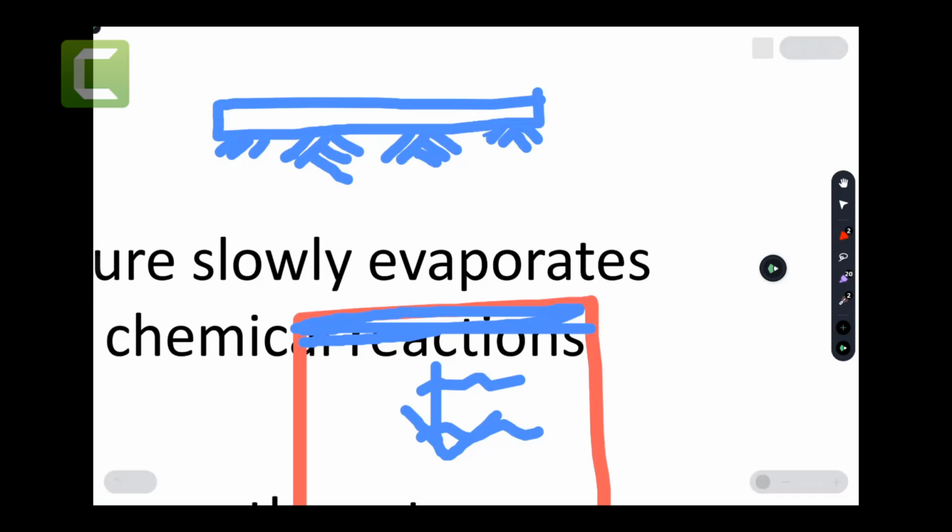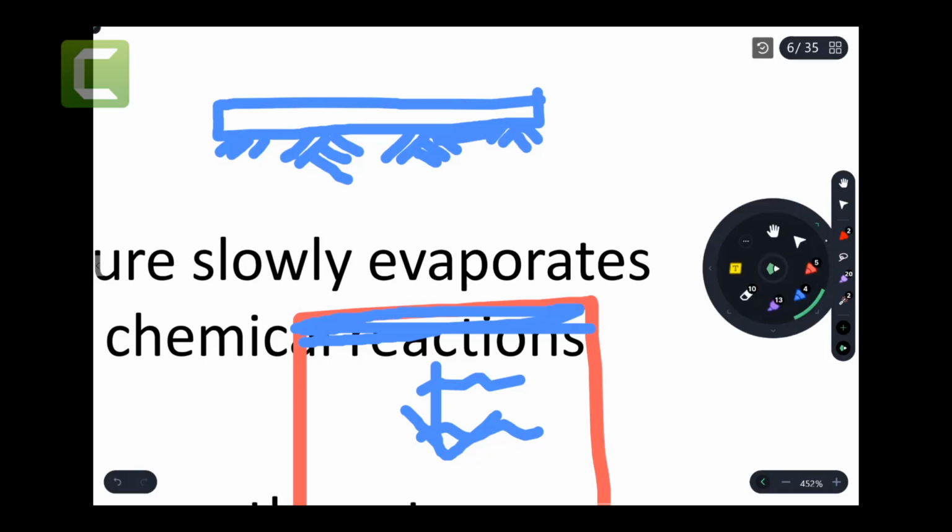However, there is actually friction. There is friction between the gray concrete and the soil, the dirt. And that friction is causing, as you know from physics, a resisting force. That resisting force can still be considered a restraining mechanism that will end up causing cracks.